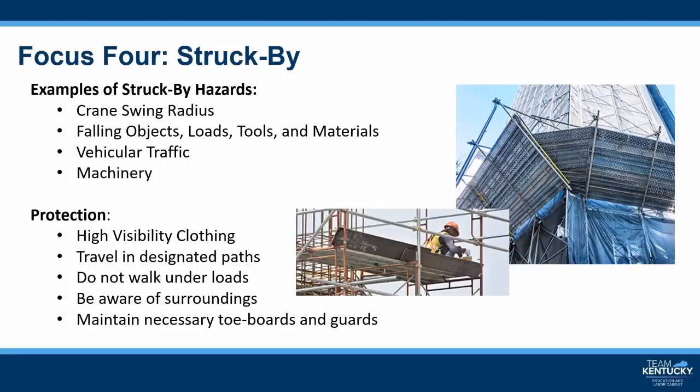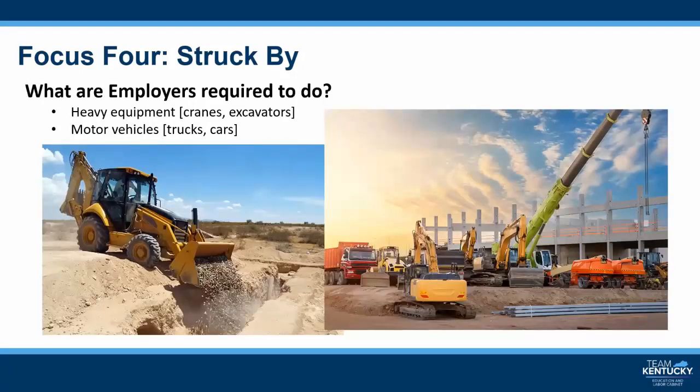Pedestrians should never cross the path of motorized equipment unless they've made eye contact with the operator and have been signaled to pass. What are employers required to do in relation to struck-by hazards? With heavy equipment such as cranes and excavators, employers must determine whether the ground is sufficiently level and firm to support the anticipated weight of hoisting equipment and associated loads.